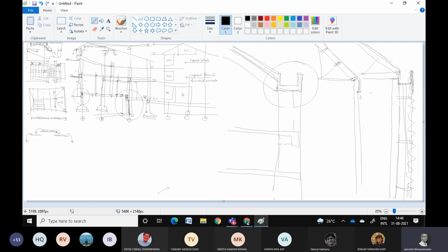When I detail, I usually give long overhangs with brackets, because long overhangs extensively protect your building windows. And where the water is to fall off, I usually create channels in the ground such that the water can be collected and drained off somewhere. So I do not give any gutters.